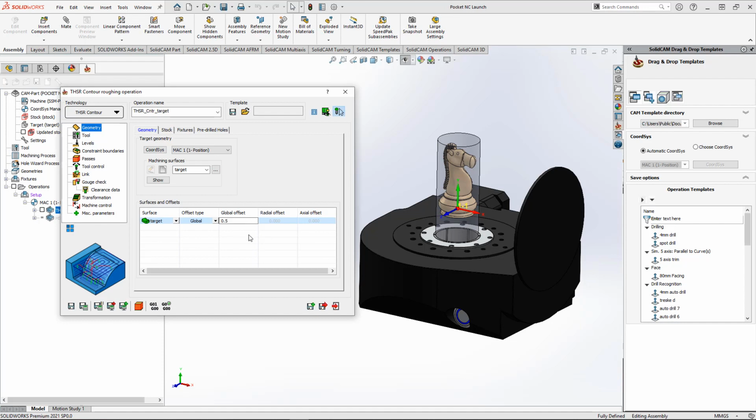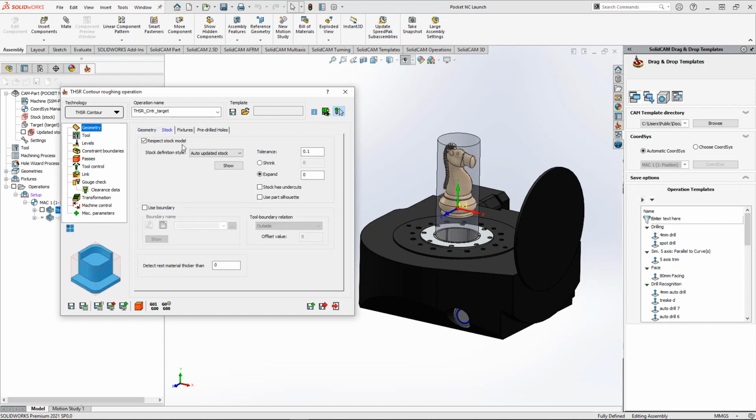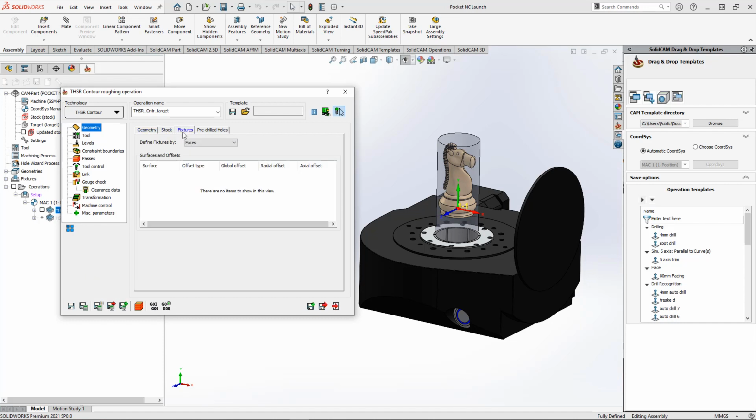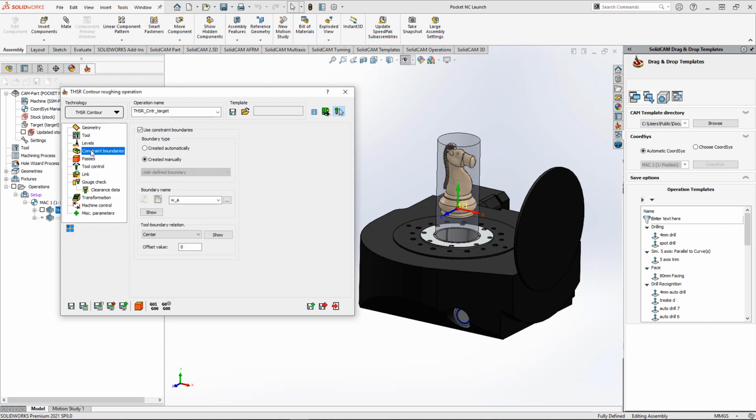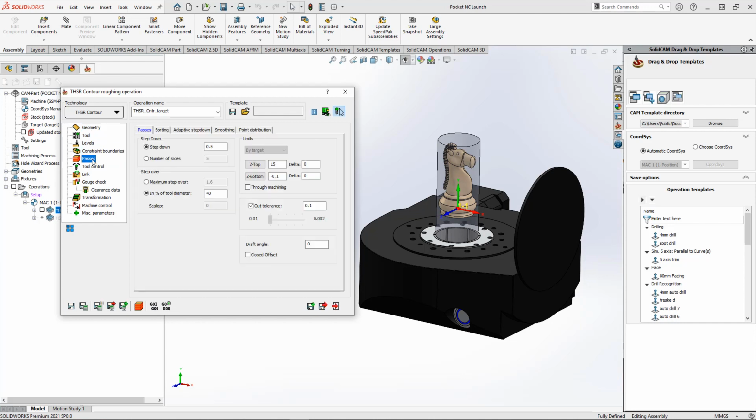Moving on from pocketing, let's look at the new strategy in SolidCam 2020. Turbo HSR is aimed at being a quicker, high-speed roughing strategy than traditional HSR. Turbo HSR does this by being a true 64-bit toolpath. This allows the user to use all logical cores of their processor, making processing time go down drastically on larger toolpaths.